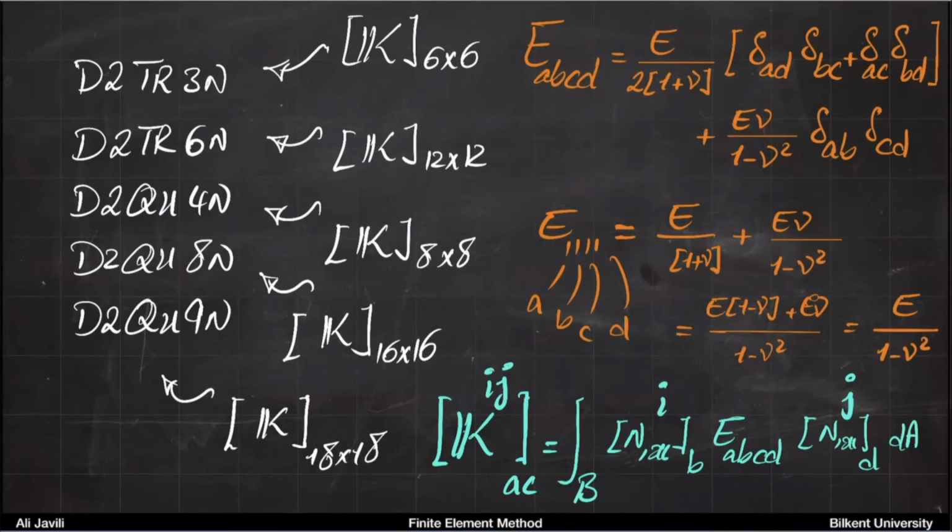So basically here, the Poisson ratio that you have, we just write it with a different color, maybe this, nu, is the usual 3-dimensional nu that you have, divided by 1 minus the 3-dimensional nu. Okay. So basically, if the real Poisson ratio of the material is 0.5, then the Poisson ratio that you enter into this formulation is just 1, okay, to get the equivalent version, right?